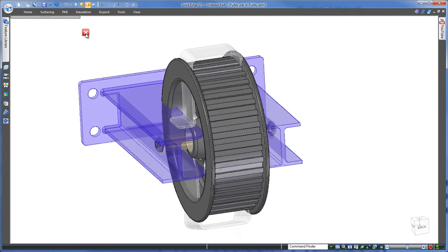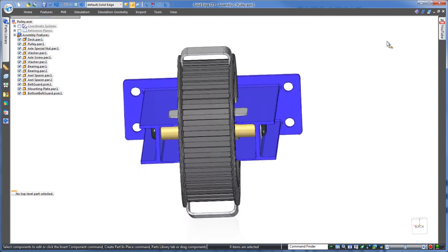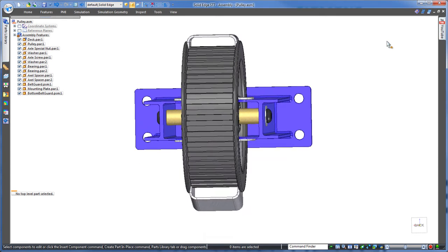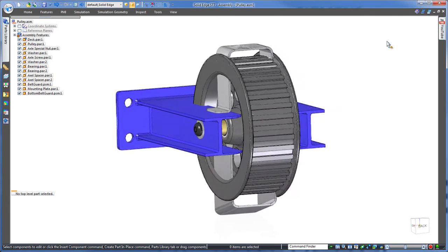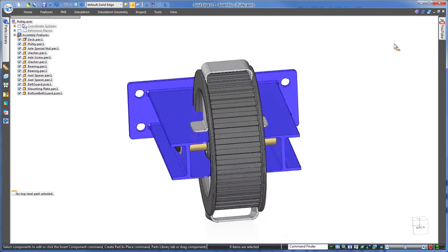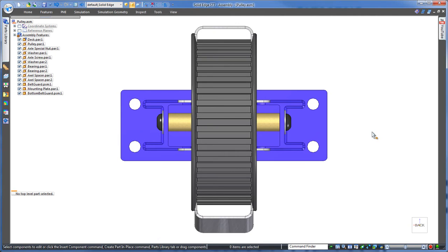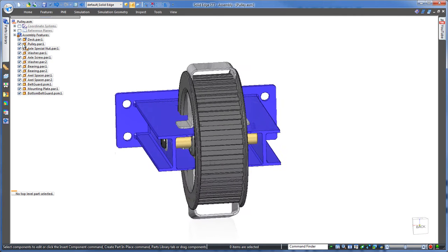So, back at the assembly level, obviously the wheel is now wider, which means it's interfering with the other components. And we have some internal parts to deal with too. Now to modify these, we could continue using a history-based approach, editing each individual part. However, this is time consuming, as you've seen. We could set up links between the parts so that a change in one part updates another. However, this too takes time.